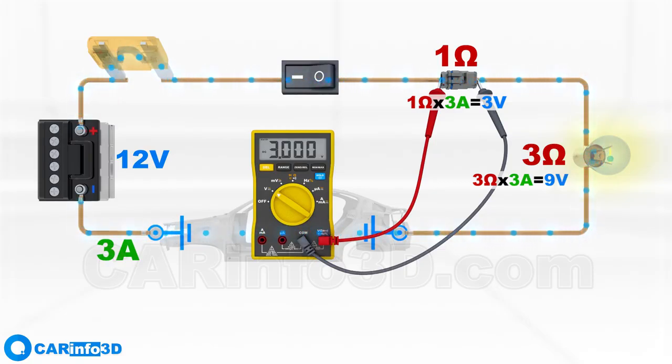It's essential to understand that voltage doesn't simply vanish. It redistributes throughout the circuit and still performs work. However, in a faulty connector, that work is no longer useful. Instead, it manifests as heat at the point of resistance. Simply put, the connector has effectively become a load, acting as a heater now. Any other component in a circuit can similarly turn into an unintended load when its resistance increases due to a fault.